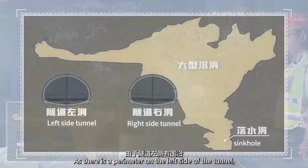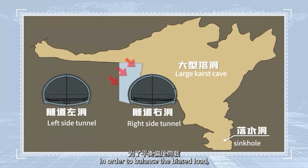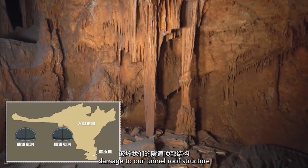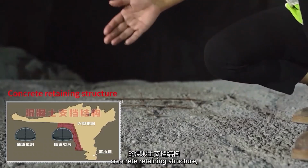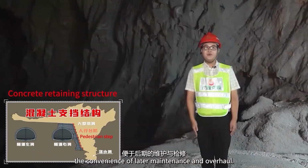The right side and top of the tunnel are exposed in the cave. In order to balance the biased load, and at the same time to prevent the roof rock of the cave from damaging our tunnel roof structure, we poured a C20 strength concrete retaining structure, which is designed as a humanoid step for the convenience of later maintenance and overhaul.